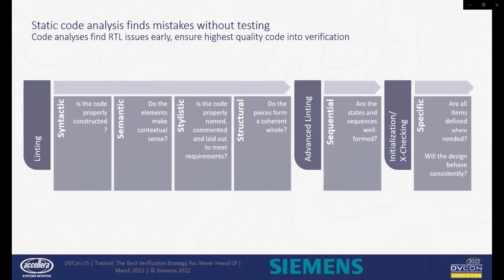Finally, further automated formal analysis is done on the RTL with initialization X-checking to identify likely unintended, uninitialized portions of the design, as well as portions of the design that are subject to X-pessimism or X-optimism, problems that might normally be identified much later in the development process.